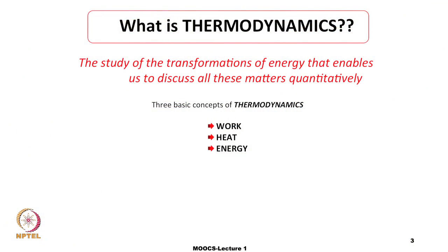There are three basic concepts of thermodynamics, three fundamentals: work, heat and energy. And out of these three, the most fundamental is work. The reason I say work is the most fundamental is that work is something you can actually see happening with your eyes. In other words, work is said to be done in a process if that process can lead to a change in height of a weight somewhere in the surroundings. I will give an example soon. Heat is another form of energy, and energy is the capacity to do work. Out of these three, the most fundamental is work, for the reason I just explained.